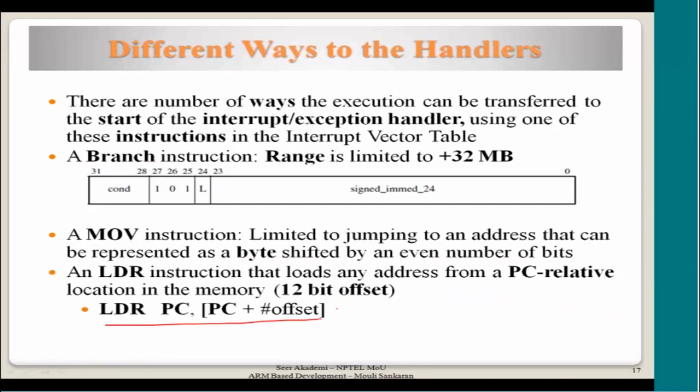Otherwise you can use LDR. LDR is with respect to PC. See, it is very simple here. The current PC, given the fixed location of the IRQ vector, that PC value, current PC value, because of prefetch may be +4 or +8. Yes, it will be +8 normally.